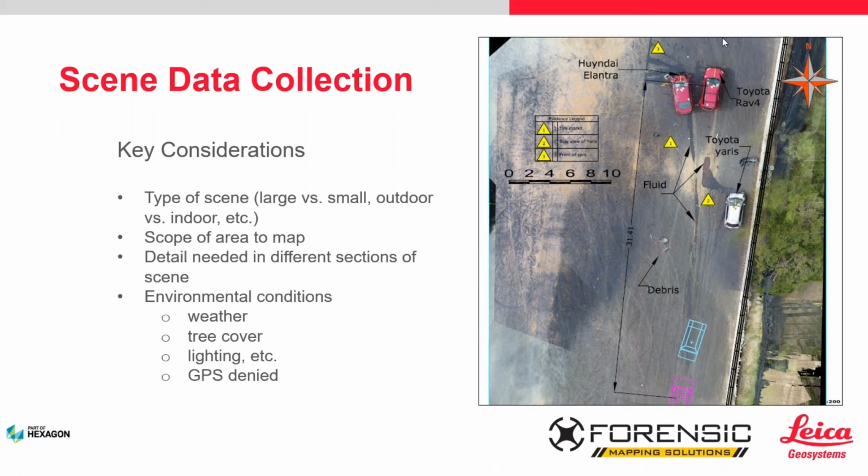But some of the scanners like the Leica RTC 360, it'll scan your points and photographs in 1 minute and 51 seconds. So the time that it takes to scan has gotten much better as well. But it's like anything else, you've got to pick the correct tool for the job.